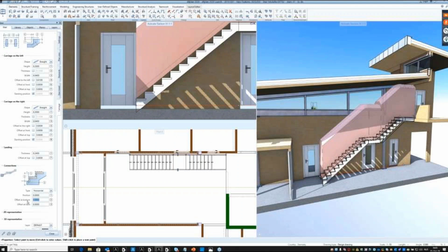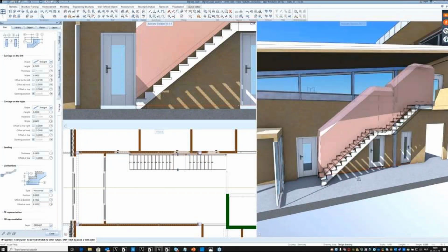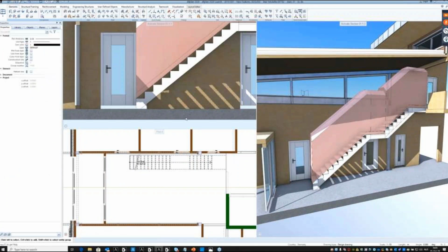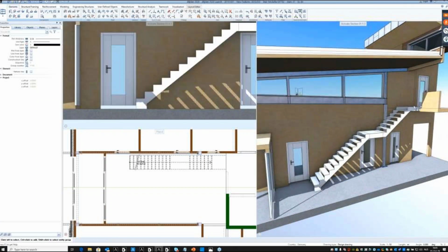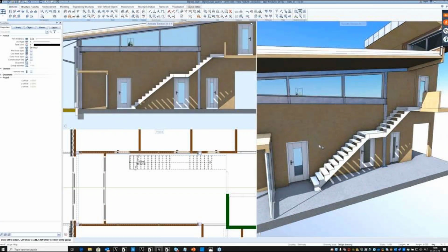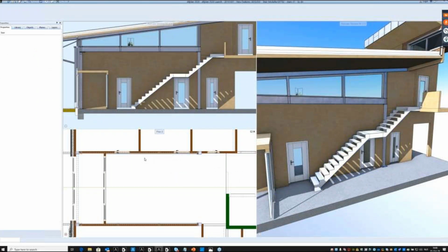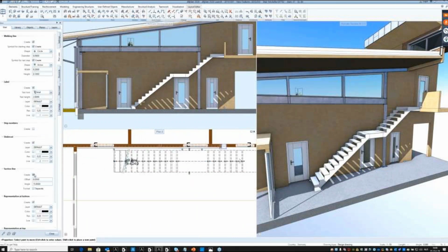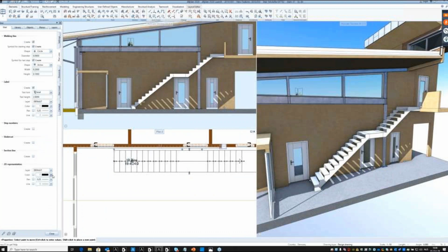And you know that frustrating small tip at the end starting of the stair, now it can be solved through the parameters. So you can chop off that tip so that you don't have to explode into 3D or things like that. The stair remains parametric, but also volume wise and for drawings you have incredible precision. And of course you can easily replace the side beams with some ramp, some slab and things like that, and create different favorites. So you can have your own favorites and adapt it through the project.